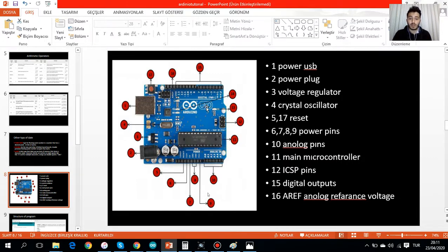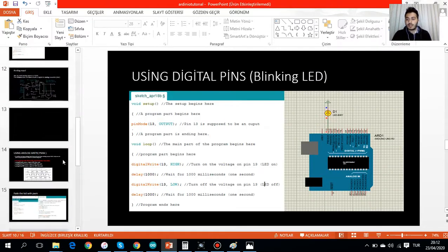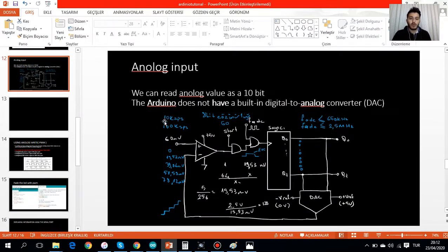But we have a PWM module that I plan to talk to you about in the next video. We can act like that. We have an analog signal by the PWM module, but till that video you should know that there is no analog signal from outside. Actually, even the PWM module is not going to be an analog signal. This is a kind of trick that we implement on Arduino. This is the first thing, guys, you should know. Never forget, no analog output in Arduino.